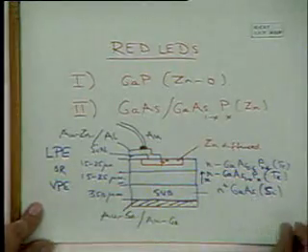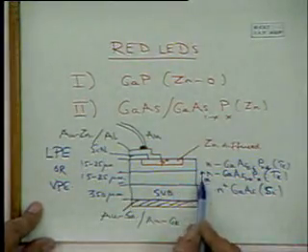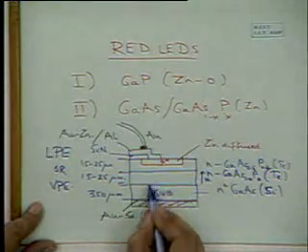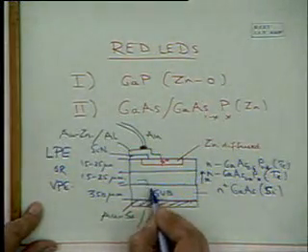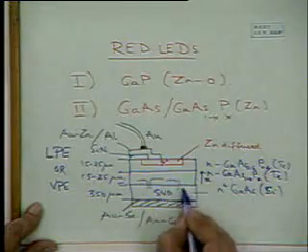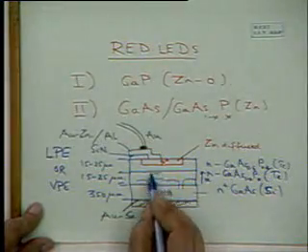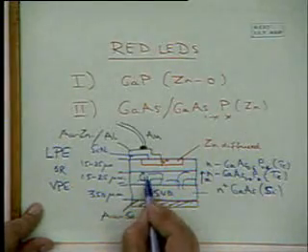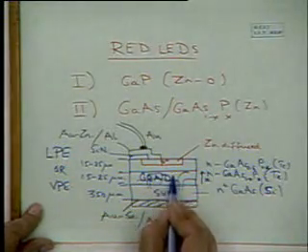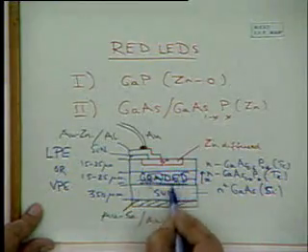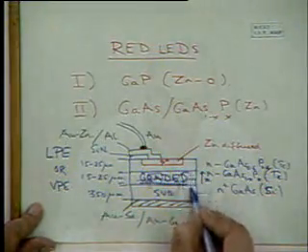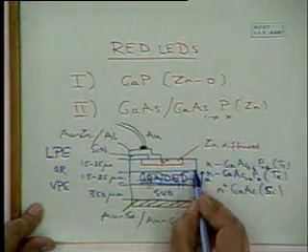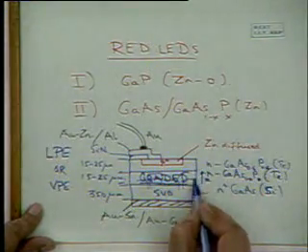And this is lattice mismatched. So if you have dislocations due to mismatch here, the dislocations hopefully will remain in this graded layer. Graded means composition varying with distance. At the beginning it's gallium arsenide, and here it's gallium arsenide phosphide. And X is changing.